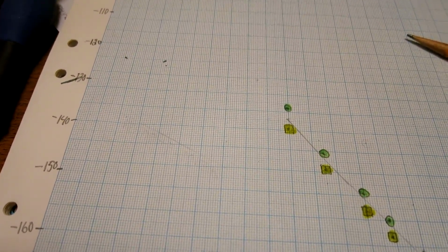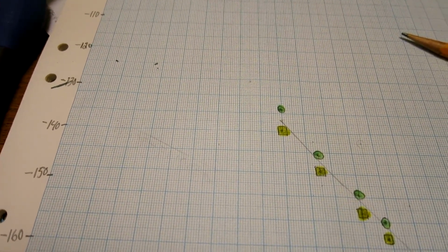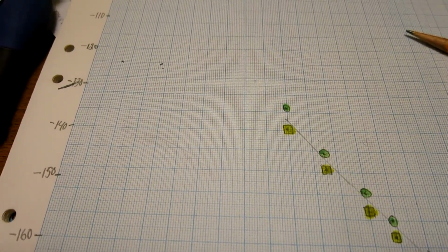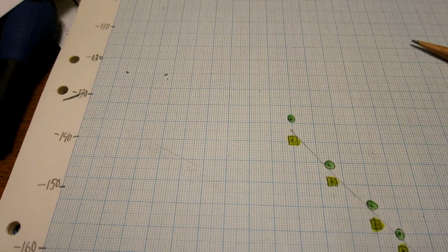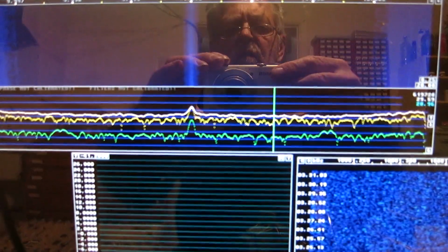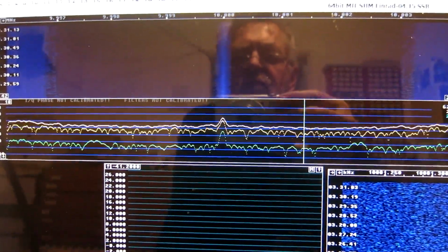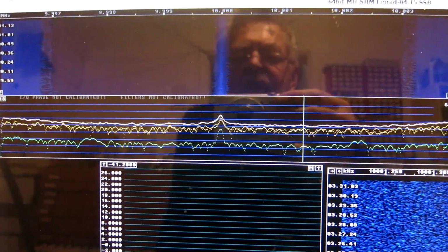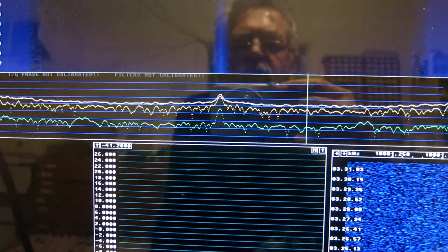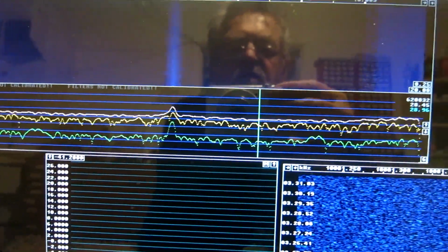So there is another solution, that is to run the sound card at a lower sampling speed. Now, I cannot do that because the lowest speed for the UADC4 is 44,100 Hz. But I can use another sound card. This is the Delta 44 running at 8 kHz. That would allow me 5 times closer. That is 2 Hz from the carrier, and that will be sufficient.